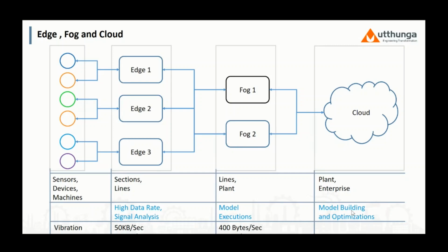And if you go by the Nyquist theorem, probably 2 to 2.5 times is what we are going to sample the data. And if the data is a float, which is 4 bytes, we end up with 52 KB of data in 1 second. And then that data will become 4.4 GB of data per day.